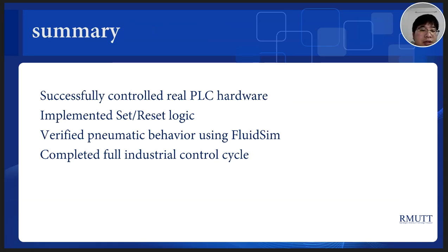In summary, this project successfully controls real PLC hardware. I implemented the set and reset logic by using the programming languages LD, FBD, and ST. I also verified the pneumatic behavior with FluidSim simulation.